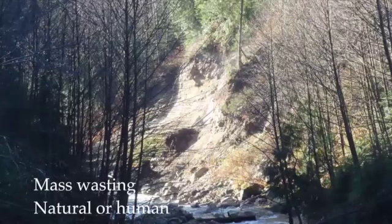When looking at this bend in a stream, as shown in this slide, you may think that, of course, there's undercutting from this stream, and that this slumping into the stream is a result of natural processes. The way a geoscientist looks at that is, yes, there will indeed be some mass erosion, but if there is some artificial road water being generated upslope that is running over the head wall of that bank and causing it to fail, then we will have to say it was being accelerated by human disturbance.